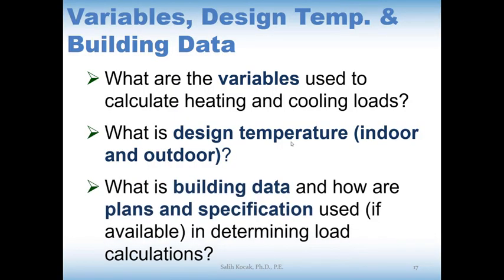And another thing is the building data. What is building data, and how are plans and specifications used in determining load calculations? Building data is the name of each room, running feet of exposed walls, and the dimensions like the ceiling height or exposure of each room to the sun, like the orientation, the compass directions and everything.